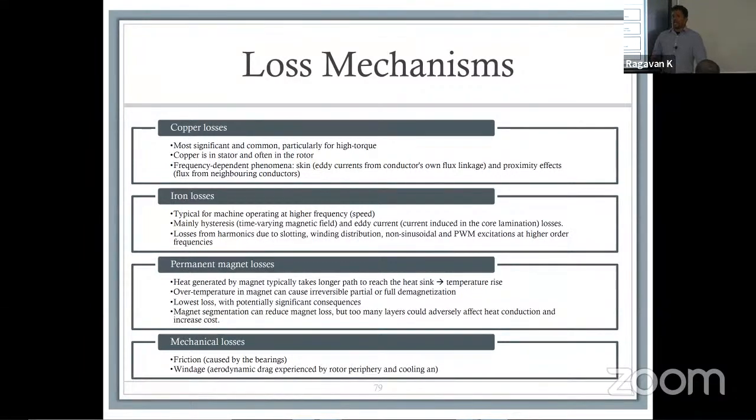In any scenario, you're trying to get the most amount of field flowing from the stator to the rotor, because you want the least amount of losses. With EV traction, the added challenge is that you also get a lot of vibration from the shaft or from the mounting assembly itself. If you don't have a high quality bearing, at speeds of 10 to 15,000 RPM up to 18,000 RPM, you might end up with a clash between rotor and stator. That's a secondary problem that is not unique, but it's definitely very particular to traction motors.